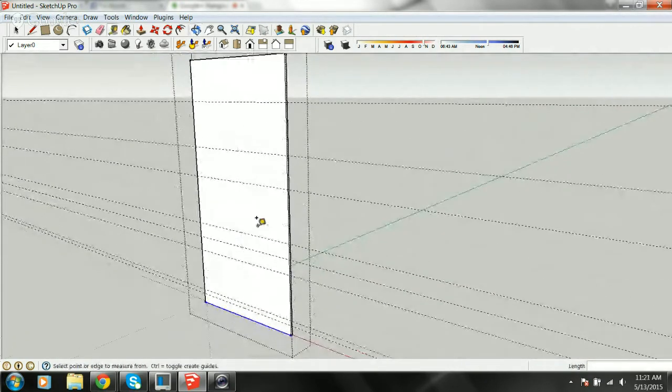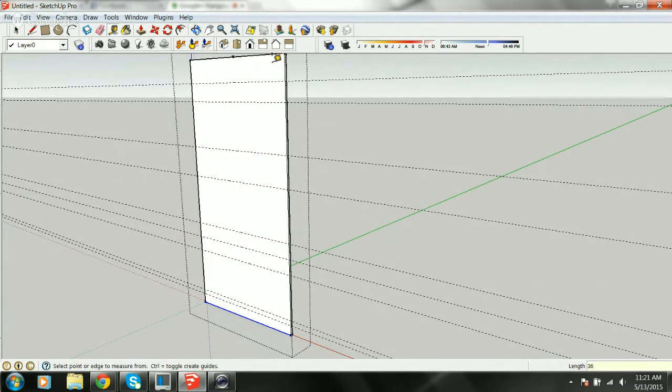So real quickly, you see all I'm doing is putting layout guidelines within my group. Okay, and then the next one was 30. I'm trying to point to my image here. So you see me go down off to the left. That's what I'm doing. I'm going to come from the top down since my cornice line was at 31. I'm just going to come down 3 feet to 36. So that last 3 feet up here is just a guideline for me within this total wall plane of where I'm going to build my cornice.